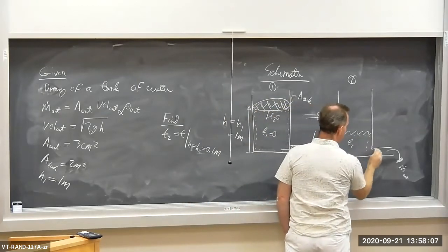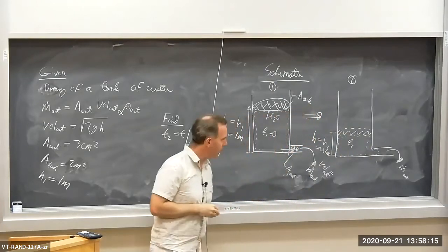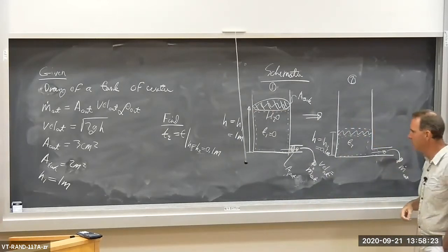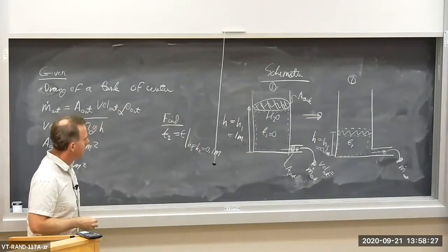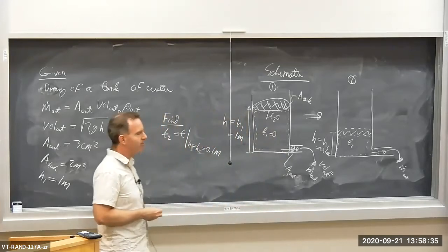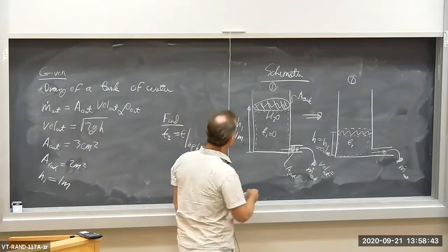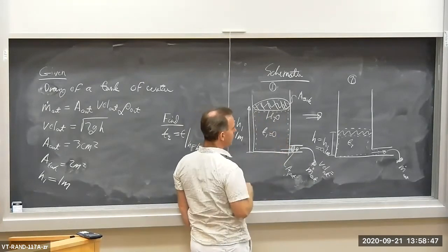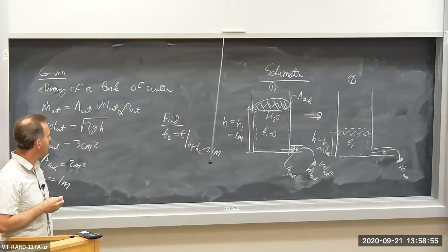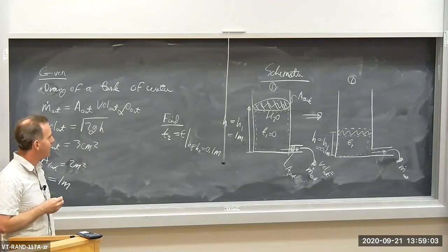Here's our system or control volume. So there's our system right there. And clearly we have mass flow crossing the system boundary at the outlet. So this is the outlet here. There's no inlet. The system is composed of the liquid H2O, so the system is shrinking. The volume of the system is shrinking over time as we drain some of the fluid out, all right? Okay, so we've defined the system as encapsulating the liquid H2O inside of the tank, and over time H2O leaves the system at the outlet at the bottom. We want to know how long it takes to drain 90% of the H2O liquid away, starting off with an initial height of 1 meter.